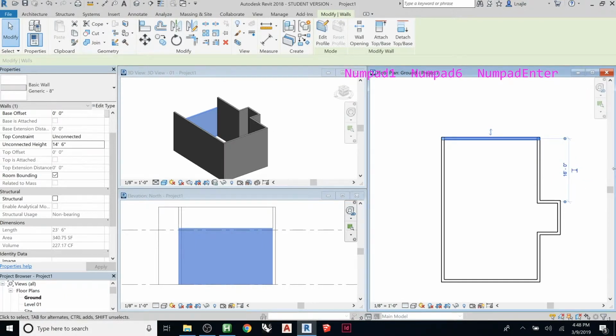So anywhere in Revit you see a dimension, it's not just a dimension. It is a dimension, but you can click on it and move things using that, or align things using that, or change the properties. So it's really important to remember that those are always live, and if you change that number, it's going to affect something.